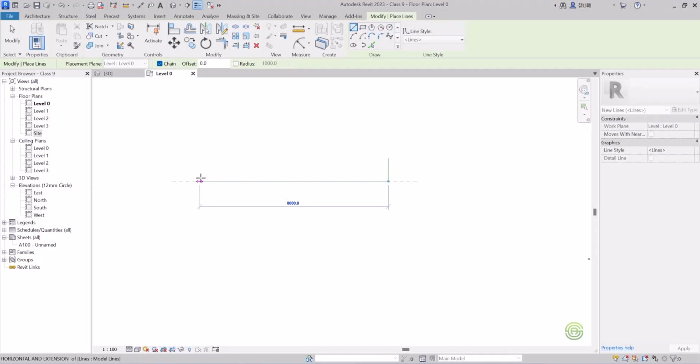So this is what the ratio depends on. Now it is known as 1:8 ratio. Now if you travel 10 meters distance to reach 1 meter height, you are traveling 10 times the distance of that 1 meter, which is known as 1:10 ratio. So this is what a ramp ratio is. The slope will be like this. For 1:10, the slope will be like this. So this is what slope ratio is all about, right?